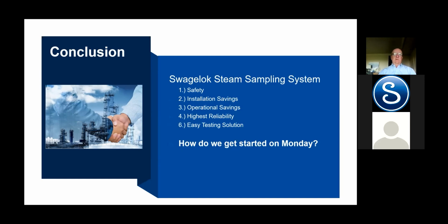One of the biggest things in utility operations or boiler operation is that people complain about steam sampling valves leaking. For one thing, you're buying a valve that already leaks, so you have the problem to begin with, brand new out of the box. So understanding the internal leak rates is very important. The second thing is putting in a valve that will take the pressure drop that we're looking at. Many times I'm working with these, we're taking pressures of 900 psi going down to 0 psi. The valve goes critical, so we have to do certain things to stop the valve going critical. If we do that, the valve gives us long life and it's very reliable.